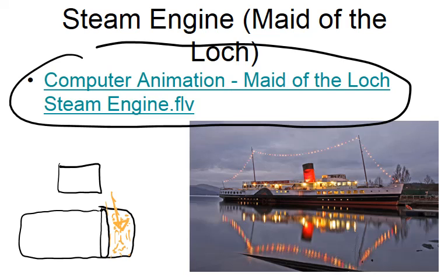It's ducted through in a specific way, and then this piston moves in this direction. As it does, it's moving cranks and then eventually moves the paddle of the ship. This hot steam pushes it this way, so it's doing work on it. Now, as it expands, this steam inside cools down. And by the time this piston is way over here, this gas inside is cool.